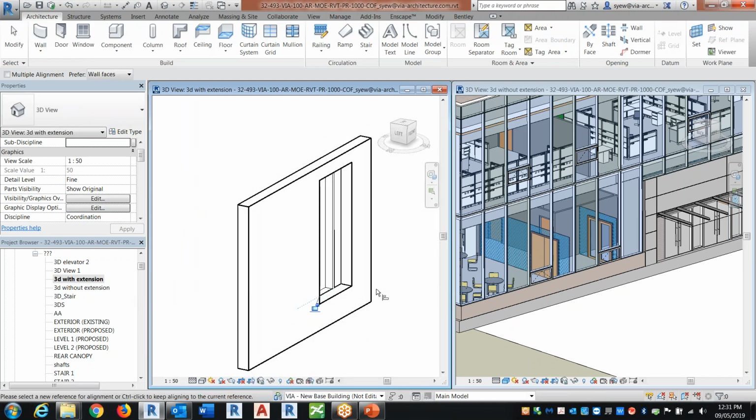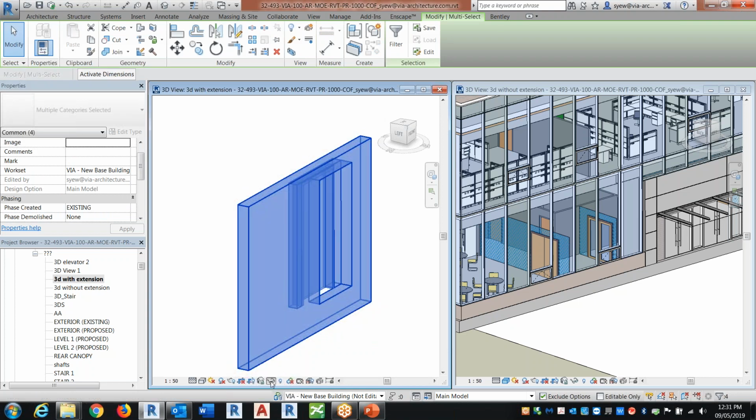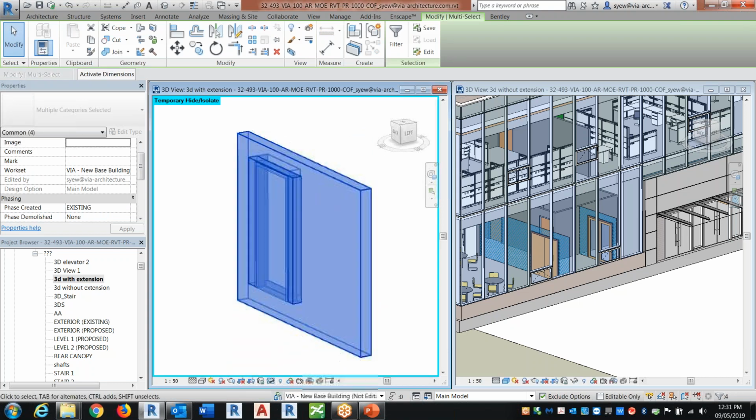I know it's a lot of steps. A lot of people say, why do we have to do this? This is how Revit behaves. If you want the phasing to look correct from demo to, let's say, existing, you have to construct it to absolute perfection. Because Revit has this tendency that if you demolish it, either you demolish the whole wall with that thing, or you demolish the door itself and put in a new host. But you pray that nothing's going to happen to that object, but unfortunately Revit will tell you later on, if you make changes, that it cannot move the wall or it cannot move the door because you have an object in there.